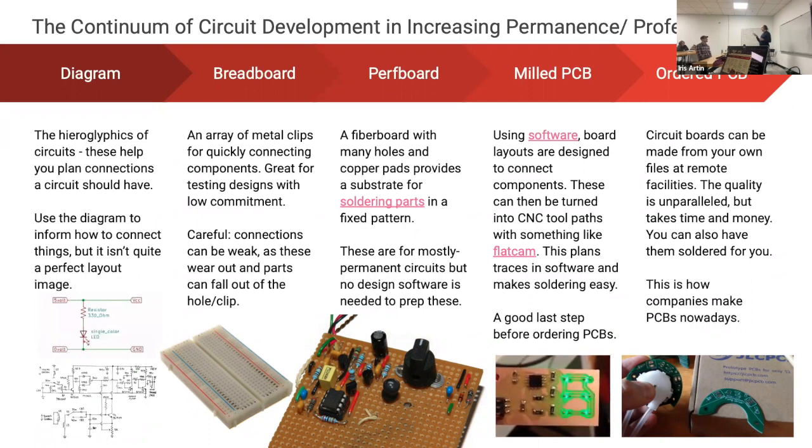And so you will go and get one because what it does for you is that it makes prototyping much faster. You can make changes to your board and you turn it around within an hour or so and you see your changes. And then once you've validated your board in-house with that kind of setup, then you can go from design files and ship them off to a PCB fabrication facility. And now you have much higher confidence that the thing that you get later is actually going to work.